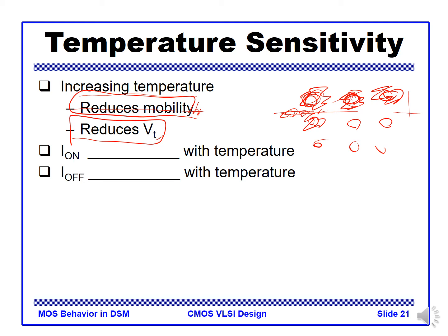Because of the structure moving around, a slight amount of current can easily flow, so the state is not stable. So even with less VGS applied, a small amount of current, more leakage current will flow for increasing temperature.